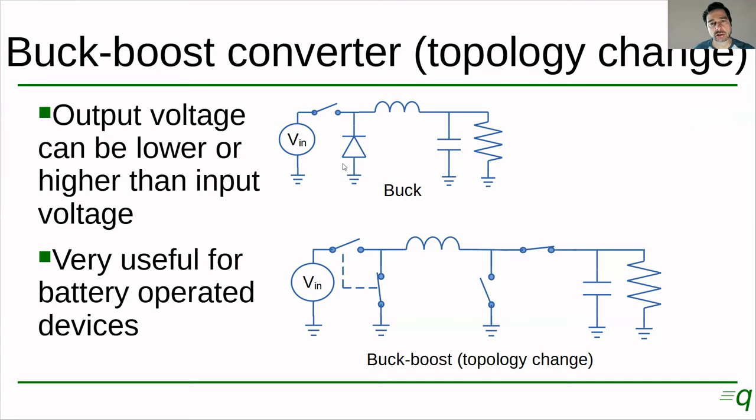So if you recall the function in the cycle of the buck converter, when we close the switch, we had current flowing through the inductor this way, from the source through the inductor to the load. When we open the circuit, the diode was providing a conduction path, right, like here. So the diode was conducting only when the switch opened, but not when the switch was closed.